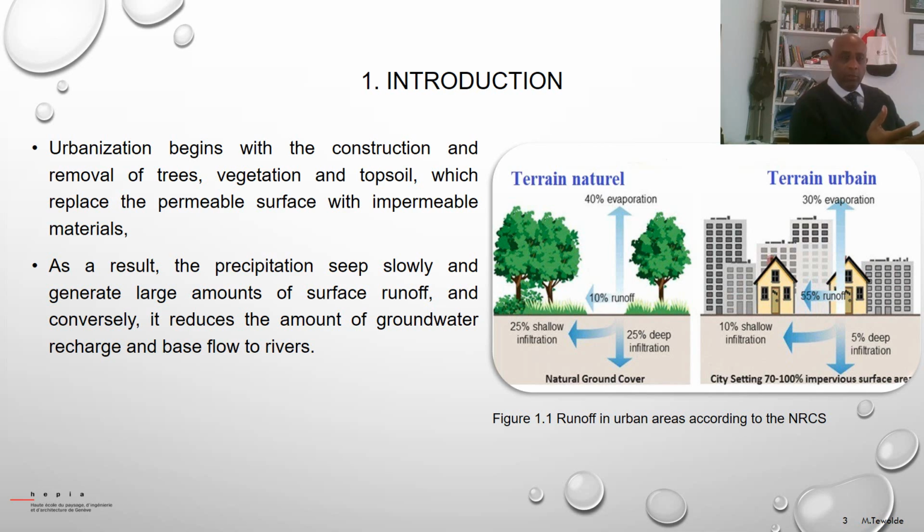That is the effect of artificial activities in a city. Whenever we build structures or build a city in urban areas, we change the structure of the soil. As a result, the volume of the runoff changes, and the effective rainfall increases.